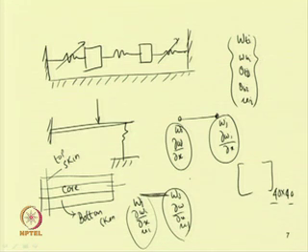When one has a large number of equations of motion, one has to use a model reduction technique. In the case of the cantilever beam, if one uses Euler-Bernoulli beam theory the equation is linear, but with large deflection nonlinearity is present in the system.